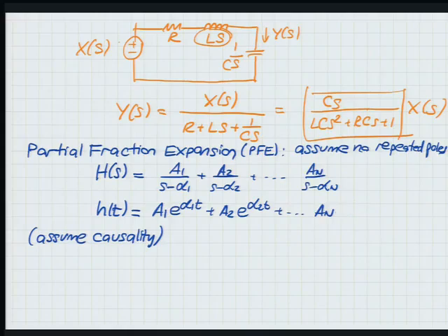Now, that tells you why we care about poles. If I excite the system, if I pulse it, somehow apply a voltage and make it disappear, right? So I just give an excitation to the system. So it will jump because of the impulse. And what are the subsequent dynamics, right? What happens next, right? H of t is basically that, right? How do you respond to an impulse? And this tells you all about it, right? If I excite my circuit, for example, it has two poles. How it reacts to it will depend on the poles. Does that make sense? Yes?